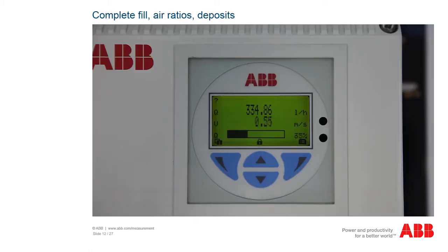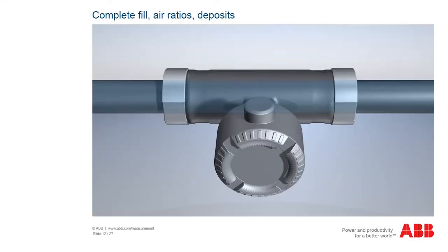If piping is not completely filled, the transmitter can display incorrect values. As soon as the electrodes have no contact with the medium, and therefore no contact with the reference earth, which is a forbidden state, zero flow may be indicated, or unrealistically high measured values displayed. If piping can run empty in the application, a detector can be activated in the transmitter. For a description, see the operating manual for the transmitter.